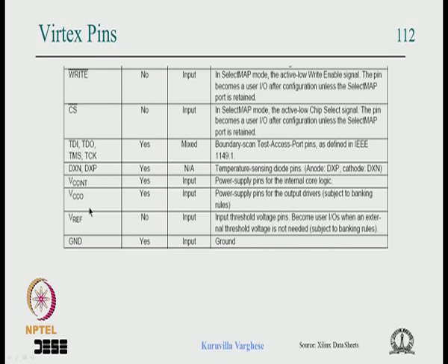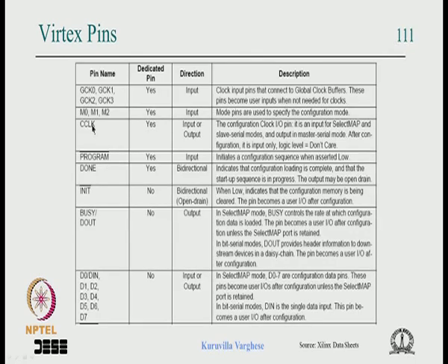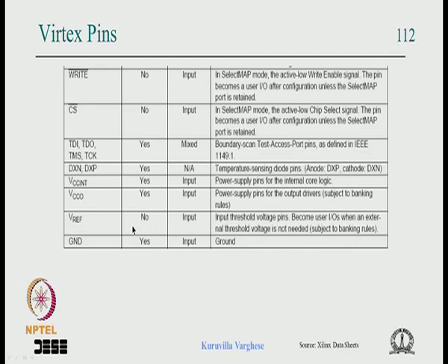So normally in the FPGA, in this scenario, you will have clock pins, some dedicated JTAG port, dedicated mode pins, and the programming pins. Some are dedicated, but most of them, once the programming is over, can be used by the user. Okay.